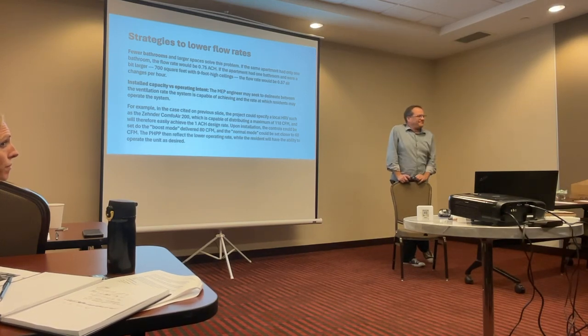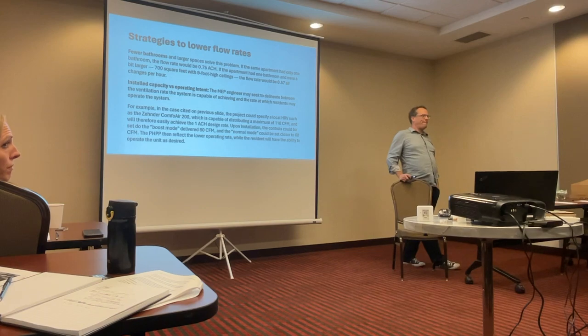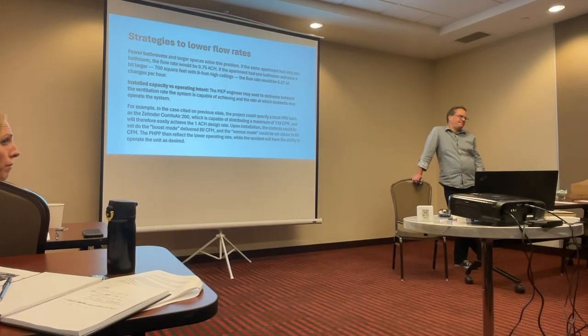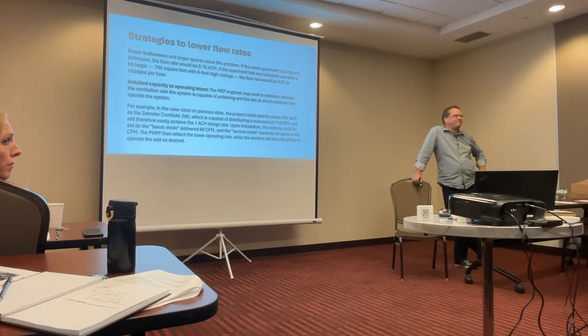Right. For some reason, over 4 stories, you have to ventilate almost twice as much as under 4 stories. We don't understand why they did it. We're working with, what's it, PNNL, who handles codes in the States, to actually take the rates for low-rise multifamily, apply them to high-rise so we can go back to the rates we were using before, and just make some requirements. Needs to be an ERV, needs to be a balanced ventilation system, no combustion in the apartment. Those are the same requirements actually for low-rise, to use those lower rates. Do you have a memo or paper on this? We can. I have emails into Kim, who's one of the people we're dealing with, so we're dealing with it in Mass and we're dealing with it in New York.